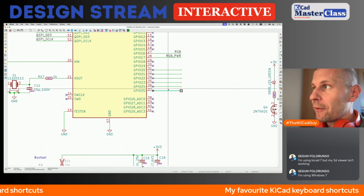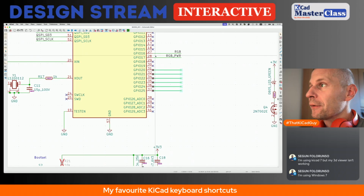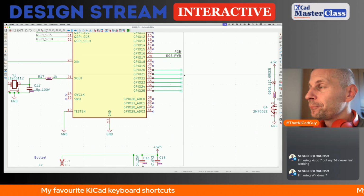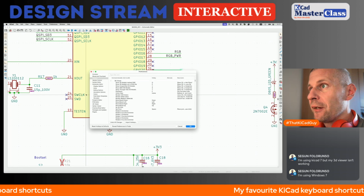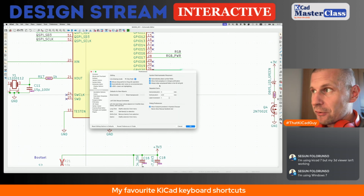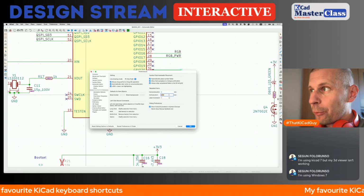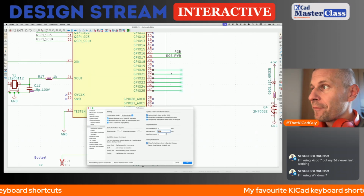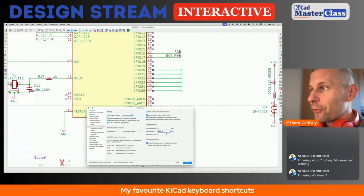So how does KiCad know how to place the lines? What is the increment? Go to settings. Here are the editing options, and here is the repeated items section. Here are horizontal pitch and vertical pitch. The vertical pitch is 100 mil of distance, so you can redefine it.